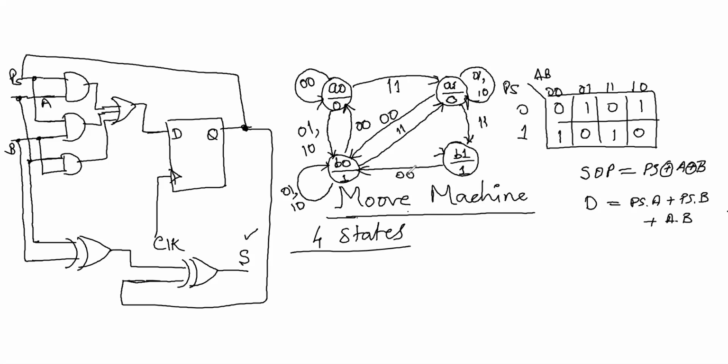Okay. If you have the other option, which is 1, 0 or 0, 1, added to partial carry will make sum as 0, but partial carry as 1. So this is the state where partial carry is 1 and your sum is 0. Only one option is left out, 1, 1, added to 1. So it is the same state. So I have drawn the complete state machine using Moore machine.